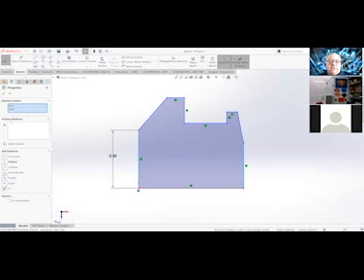So I know they're in the sequence. And then I look at existing relationships. There's not a relationship between these. There's nothing about them that's the same other than that they're vertical, and that's not a strong enough relationship to hold them together. So what I do have is other relationships I can add to these. You can pick lots and lots of different things, but you want to make sure you're controlling which ones you're using. If I put an angle line in here, that would be kind of awkward. First of all, it's not vertical, and it doesn't need to be the same length.